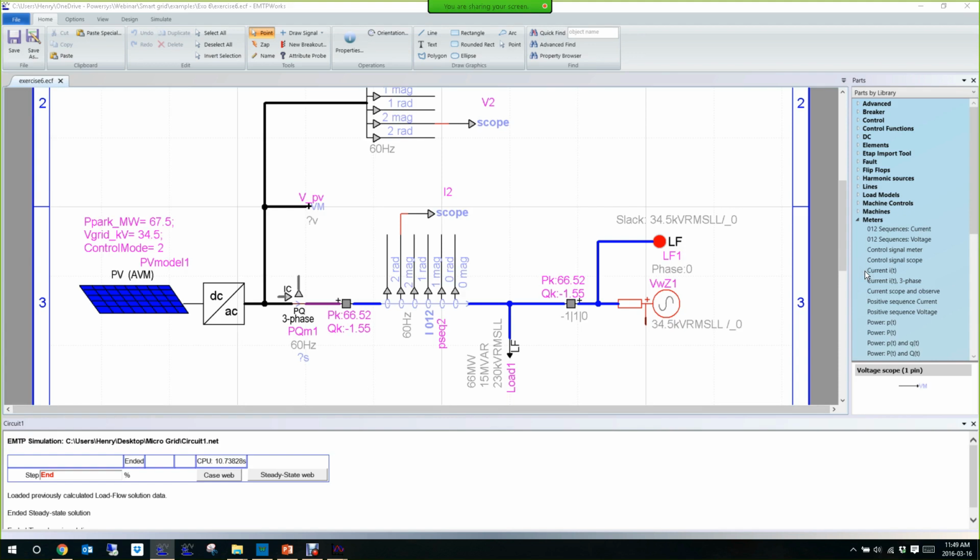So the advantage of this method, which is an active method, is that even in a very difficult islanding detection condition, so no power from the grid, we can still detect that. The disadvantage is that part of the capacity of your PV is used to inject a second harmonic current of about 5%, and you kind of disturb the power quality by injecting this second harmonic. But it's a very small level, only 5%. And again, in grid connected configuration, the voltage is very good, but when you lose the grid, then you can see that in the voltage.